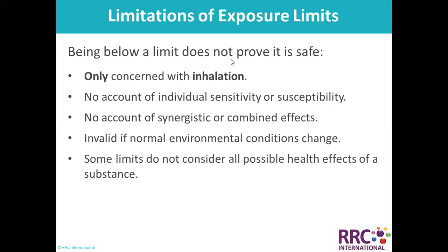Now, limitations of exposure limits: being below a limit does not prove it is safe. They are only concerned with inhalation, with no account of individual sensitivity or susceptibility, no account of synergistic or combined effects, and they are invalid if normal environmental conditions change. Some limits do not consider all possible health effects of a substance.